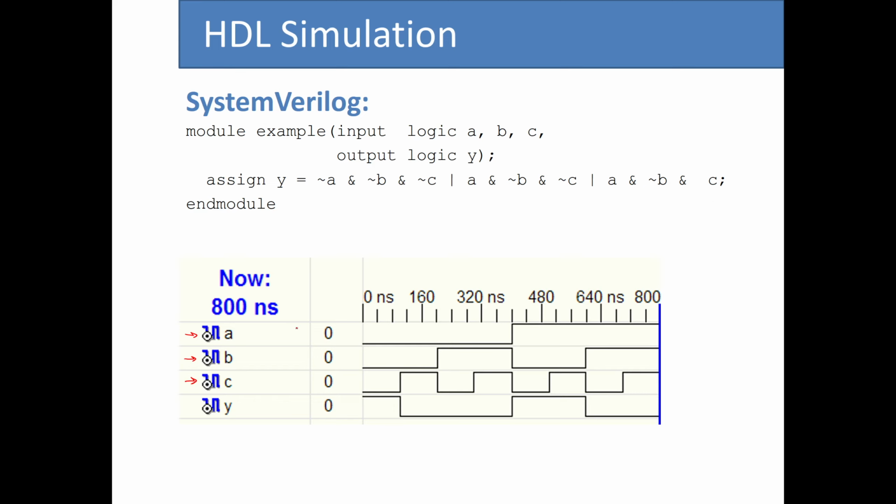if you want to create a truth table, the first row was when a, b, c were all 0, and that's exactly what we have. A is 0 here, b is 0, and c is also 0. This column is with regard to the amount of delay that we can have when we want to do the analysis, right? So for now, I'm just going to leave it as 0. I'm going to explain it later on.